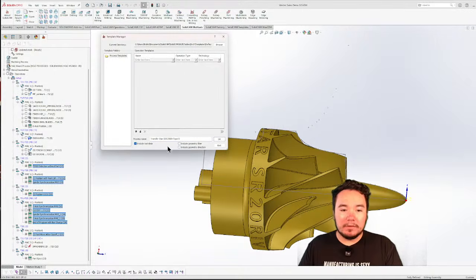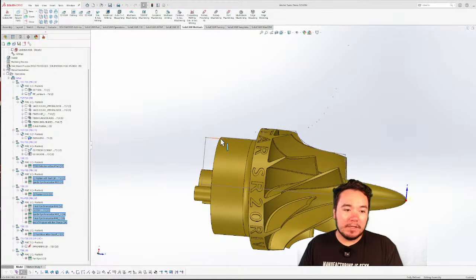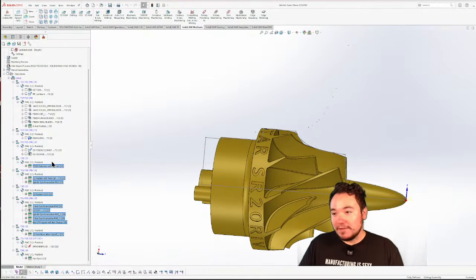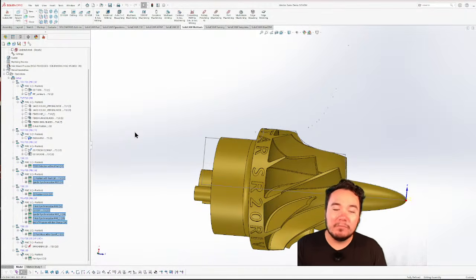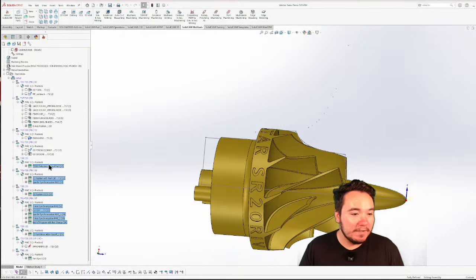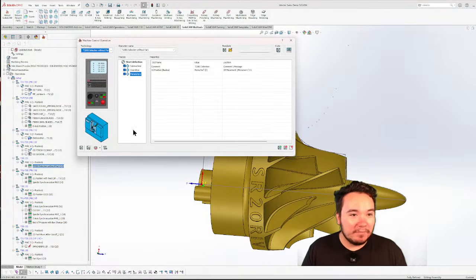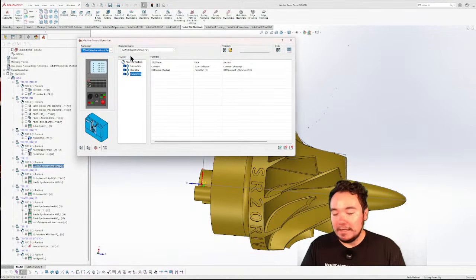And then you can do include tool data, include geometry filter if you're using the same tool for the cutoff, and you can hit OK. And that'll save it, and then you can drag and drop it onto whatever part you're doing. You're going to have to adjust just a few things, and I'll show you which parameters you are going to have to adjust. But from there, T2000 selection, that's going to home the sub spindle in line with the main. So we're ready to do our pickup.